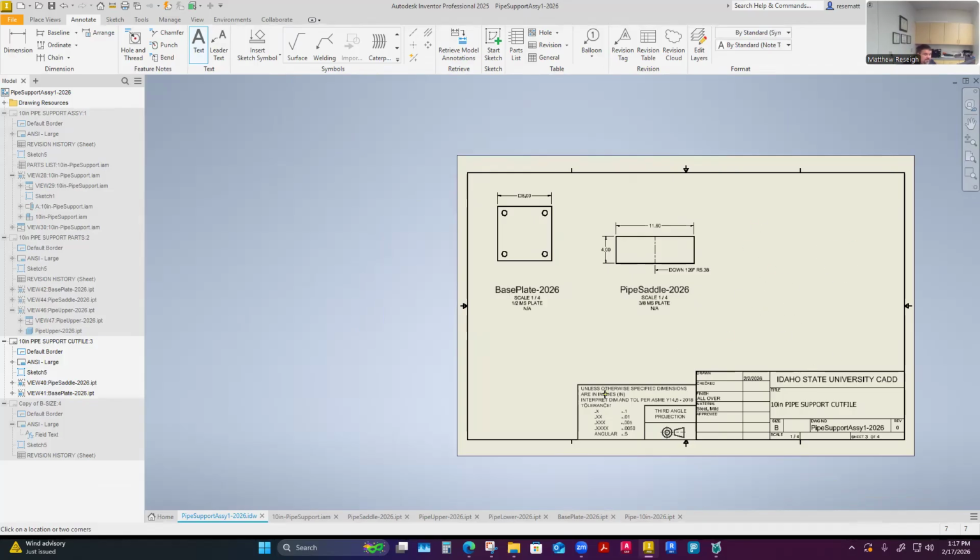And if I have multiple sheets of different materials, I'll put all the parts of one material on the same sheet, and have however many sheets of that material before I move to another material. And scale the same way. I try to use that mentality to prevent any machine interpretation error.